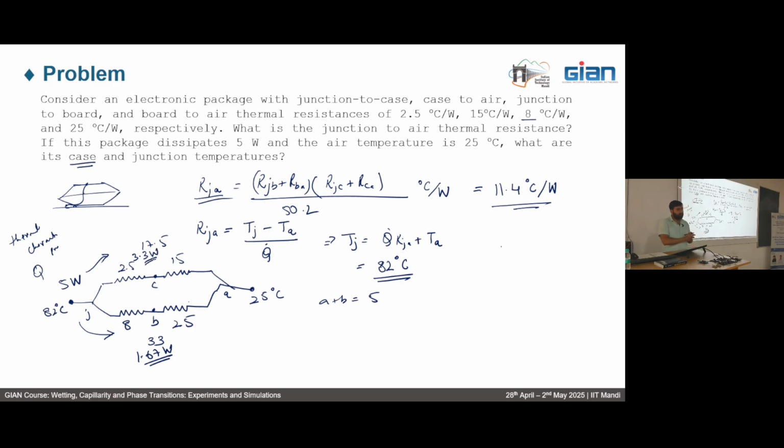Is that what you are getting? So it's always better to draw the thermal resistance diagram. Now we know how much heat is being transported from this side, and we also know the thermal resistances, so now it's easy to find the temperature. And the temperature would come out to be, how much did you get? 73. Yeah, 73 is the right answer.